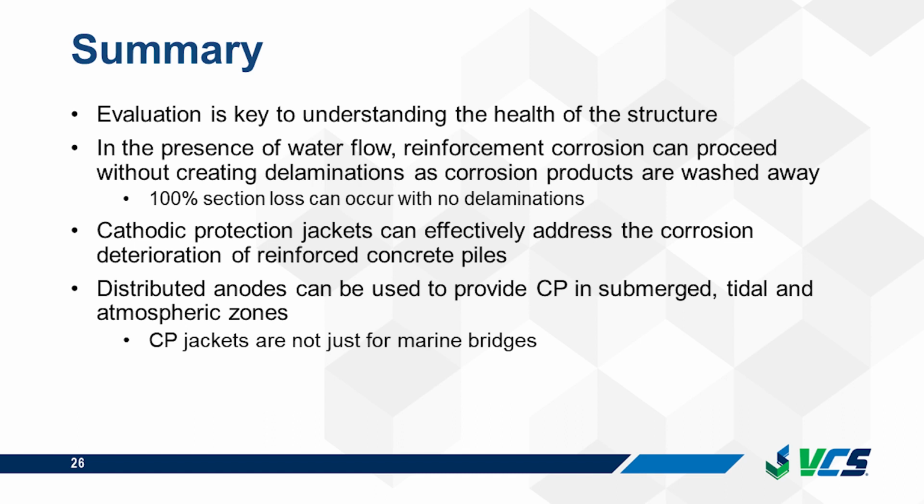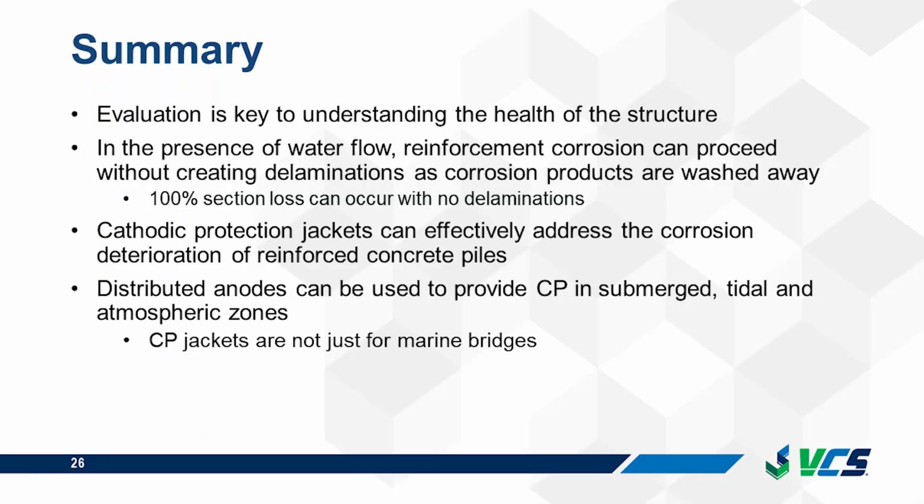So absence of delamination in the marine environment in the presence of cracking is not an indication that your corrosion reaction is at initial stages. Cathodic protection jackets can be used effectively to address deterioration of reinforced concrete piles, and using distributed anodes can provide CP in submerged, tidal, and atmospheric zones. And CP jackets are not just for marine environments, they can be used strictly in atmospheric exposure as well, with atmospheric anodes.